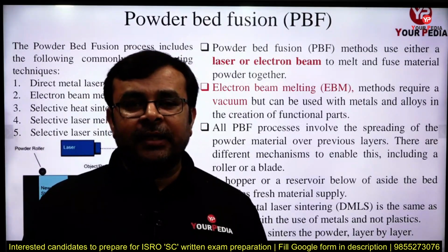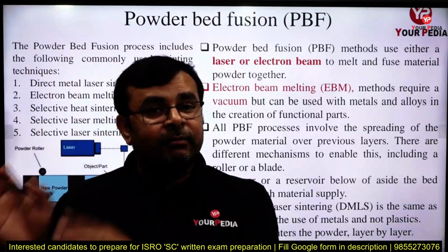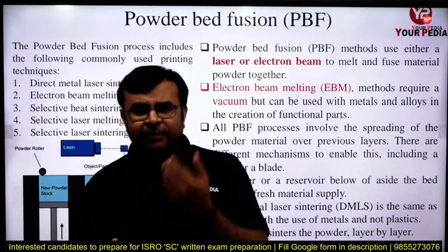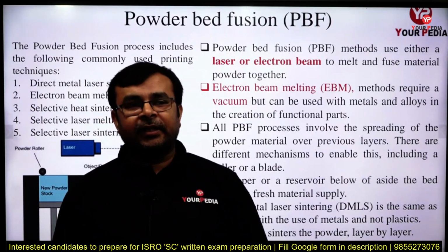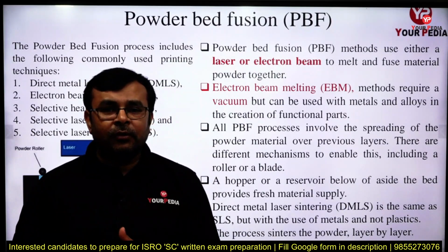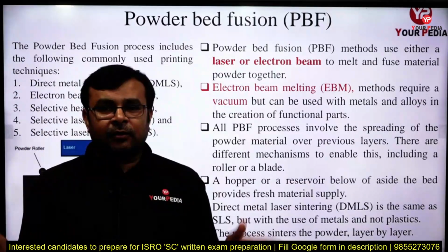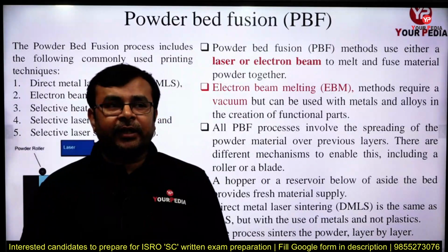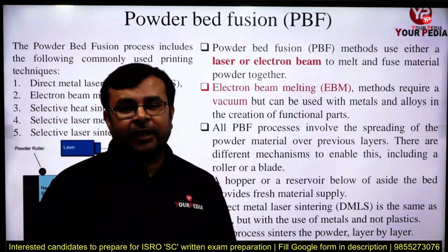In electron beam melting, or we can say electron beam welding, it is much more convenient than electron beam machining. So in electron beam welding, what we do is provide a closed vacuum chamber in which we have a cathode ring through which we can produce an electron beam.